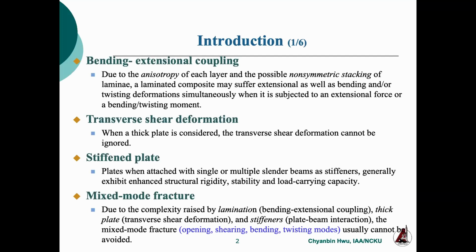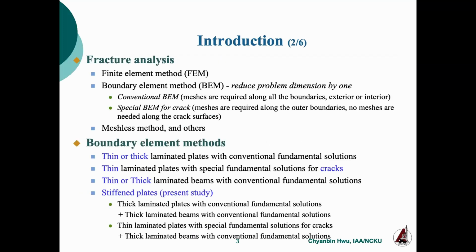So due to the complexity raised by the lamination, the bending extensional coupling will occur, and due to the thick plates, the transverse shear deformation cannot be avoided. And due to the stiffener, the beam plate interaction, the mixed mode fracture, such as the opening, shearing, bending, twisting modes, usually cannot be avoided. So the problem becomes very complicated. Usually, this kind of fracture analysis will be done by using the finite element methods.